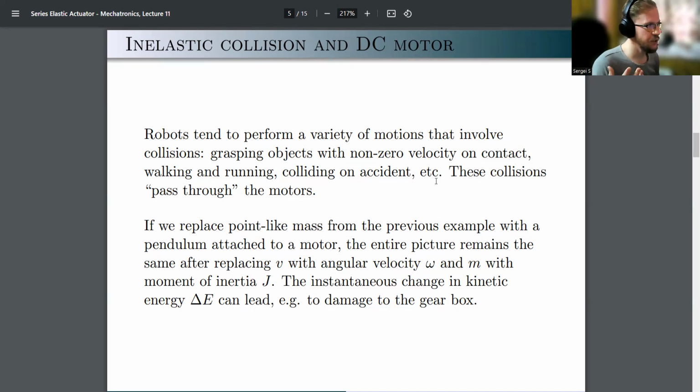But for this to work, they have to be operational during the demonstration, because if those robots are switched off, you cannot move them. Remember during the lecture on gearboxes, we were talking about how some gearboxes are not backdrivable. Well, the types of gearboxes in KUKA robots are not backdrivable. You cannot physically move it with your arm.